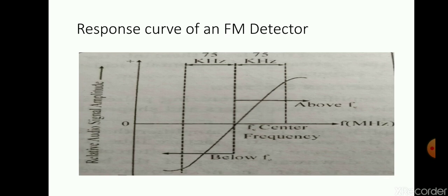The FM sound signal is amplified in the 4.5 megahertz sound IF amplifier and then fed into an FM detector. In some receivers, an FM discriminator is used as FM detector. This circuit provides an additional stage, a limiter, to provide adequate noise reduction.